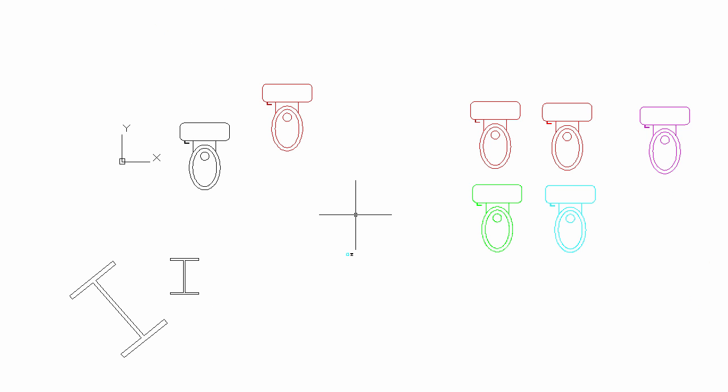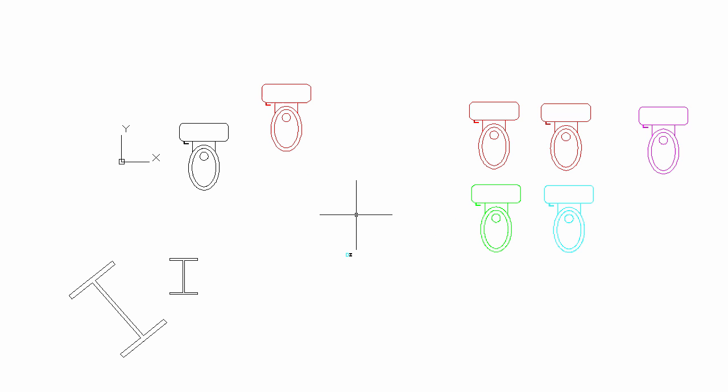Okay, so this is what we call a unit block, because I can use it for many, many things, and I can use it the same thing for like a door symbol or anything like that. So if I was to draw a floor plan in AutoCAD and I don't have fancy software like AutoCAD Architecture or Revit or Chief Architect, and I was drawing floor plans in AutoCAD, then I'd set up my drawing to draw doors and windows in this way as well.